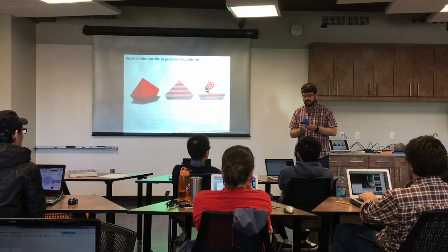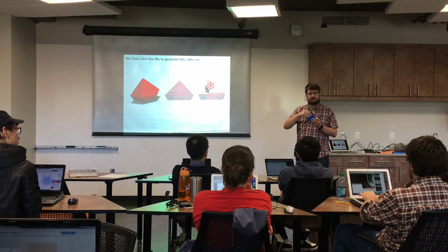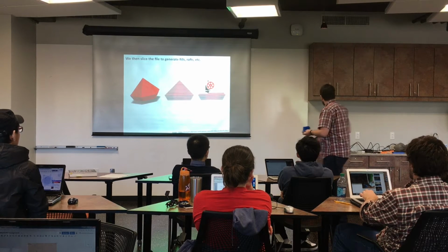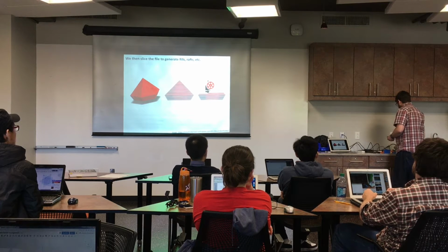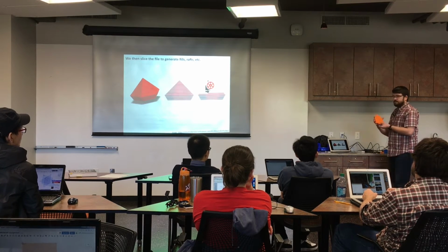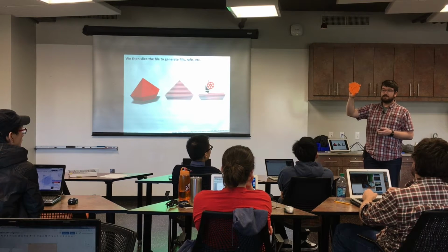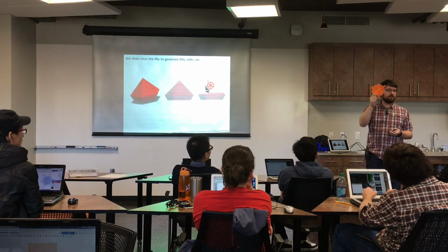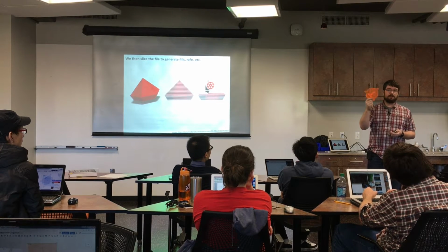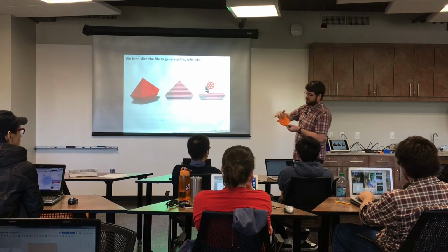Now, printing this entire thing as solid plastic would be really wasteful, and it would take a long time because it would have to travel and squirt plastic everywhere in here. So what we do is inside the part, we actually generate like a mesh network in there. You can do it in different ways. This is just a rectilinear grid, and that's one of the quickest to print. But it can also be honeycomb. It can be whatever shape you want. And you define some wall thicknesses.